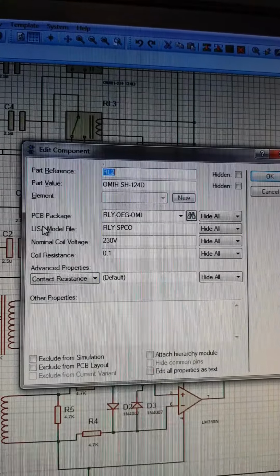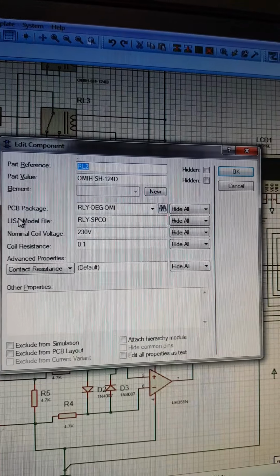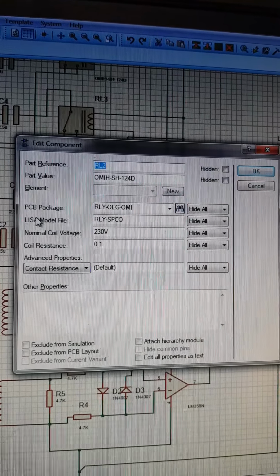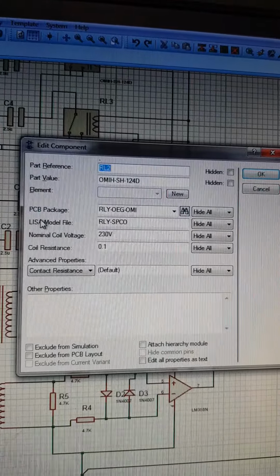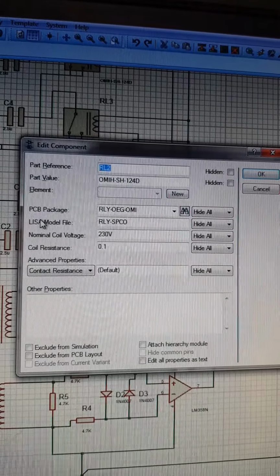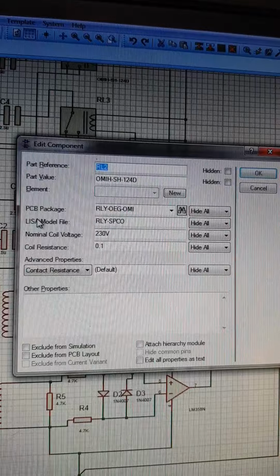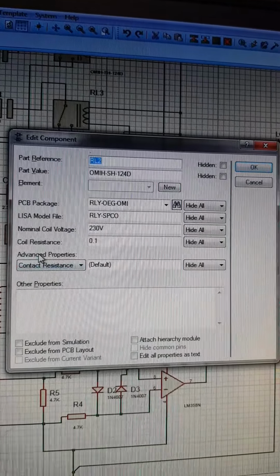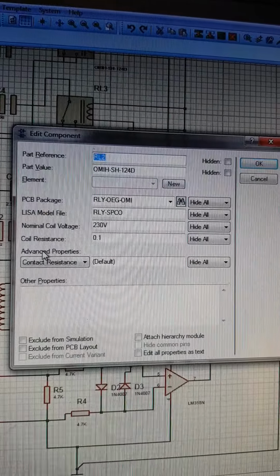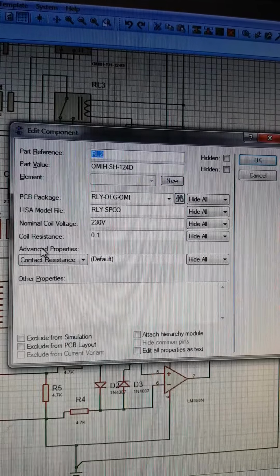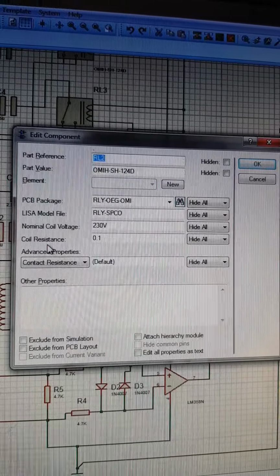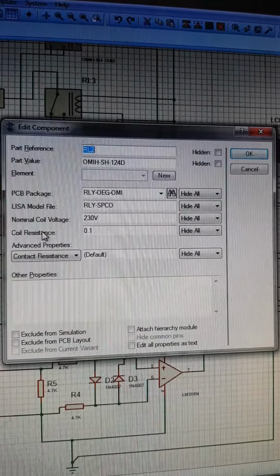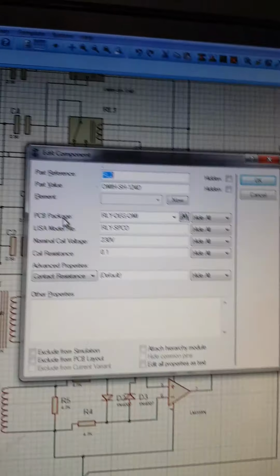There are certain times when you use a program like Proteus, you just compile your model without simulating it. If it compiles by using what we call the netlist, then you understand that even your hardware is going to work because your netlist compiled. That's another use that we use Proteus for.